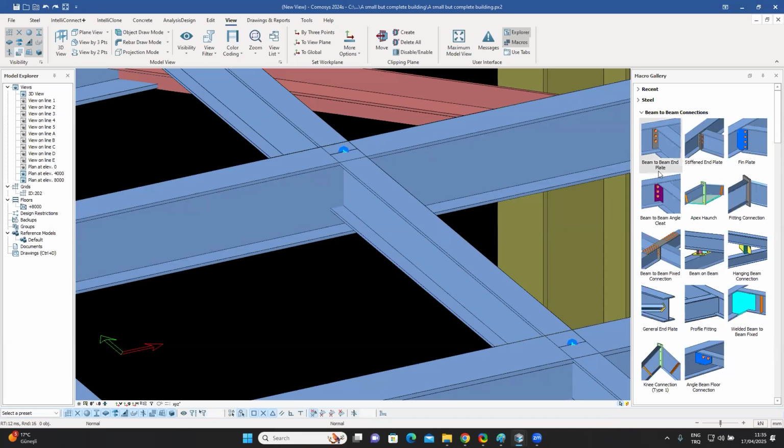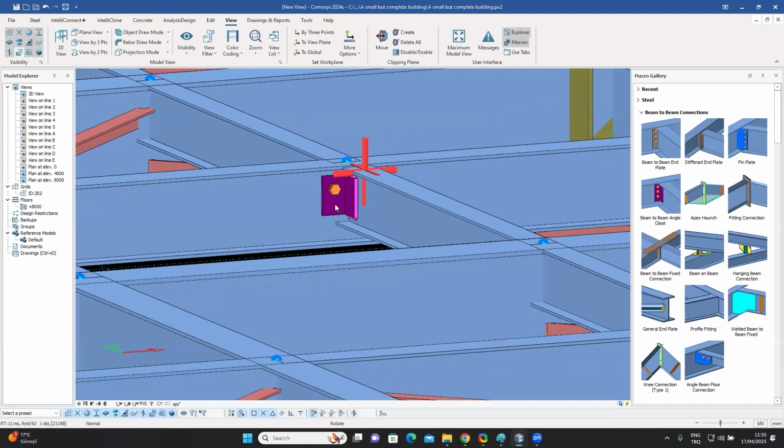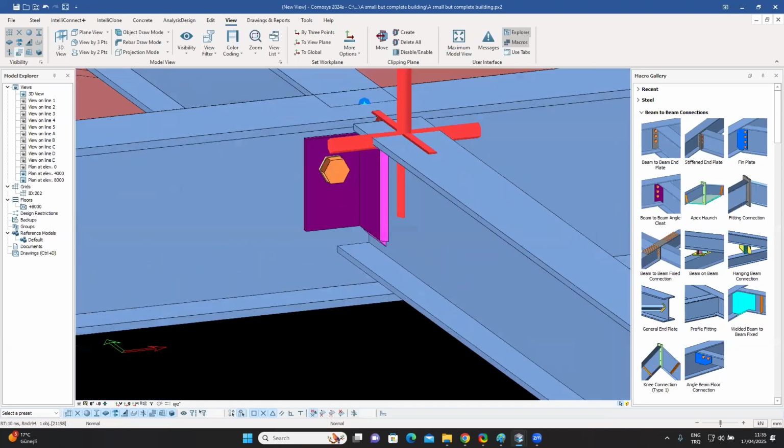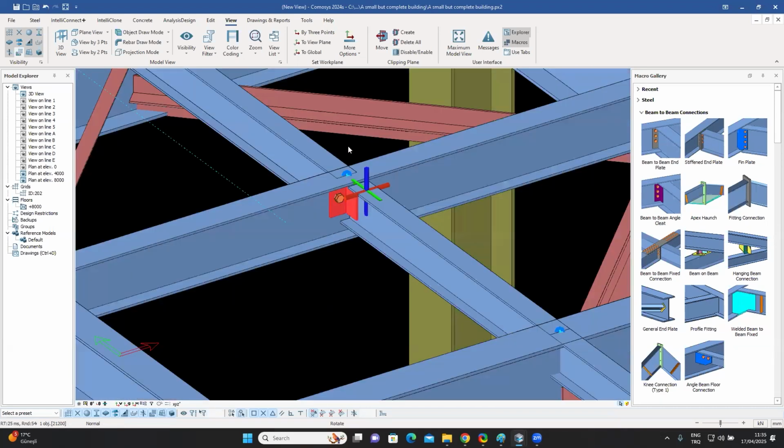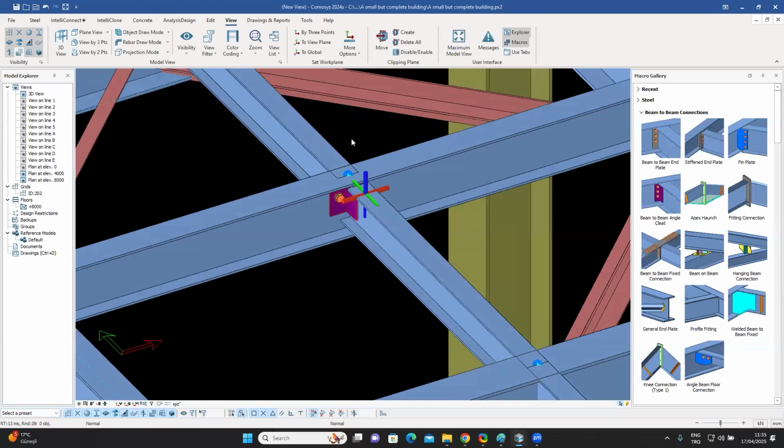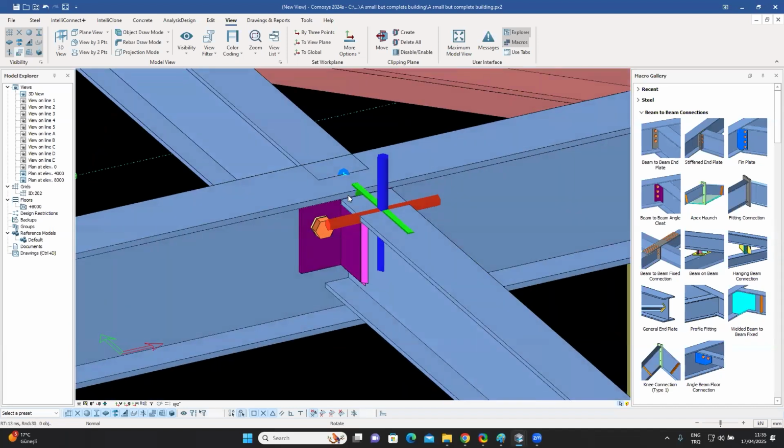not also in situations where if you have too many bolts like that, it's going to start transferring moment as well. Another option which you could use is the beam-to-beam angle cleat connection. For example, I could use the main one and the secondary one and right-click, and basically you're using angles from one or both sides. This connection is also very commonly used in steel structures.